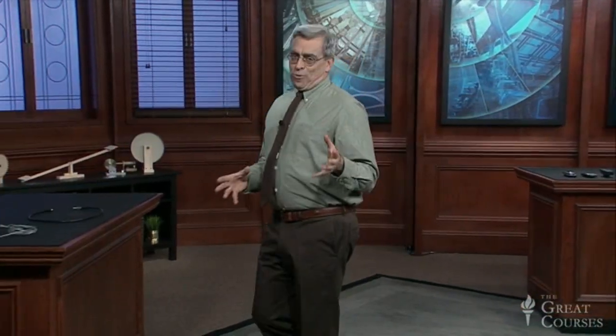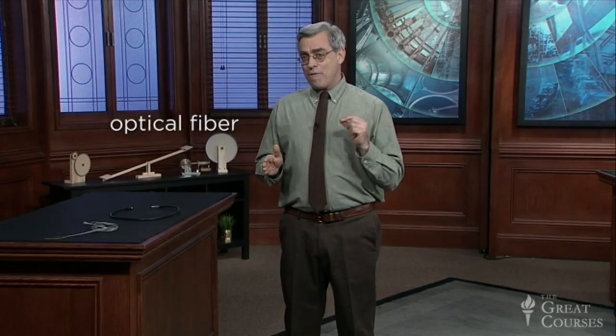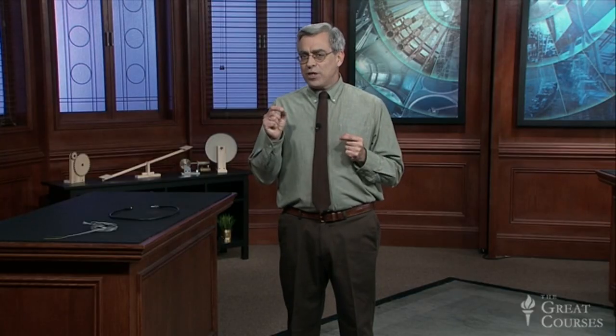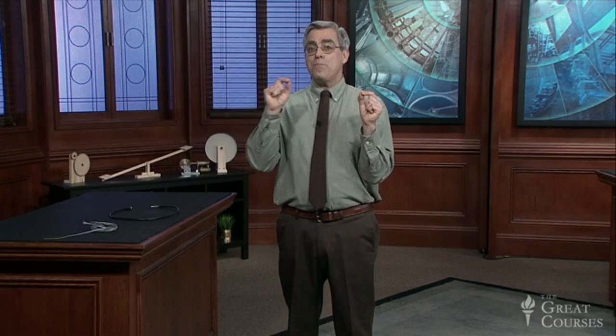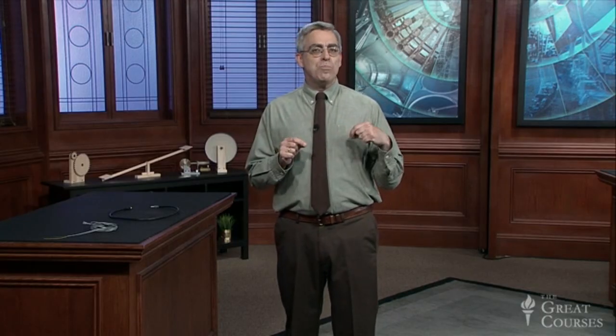But in the modern world of telecommunications, nothing is more remarkable than optical fiber. First deployed in 1979, fiber optic communication involves the transmission of a digitally encoded light beam through a tiny fiber of glass. The digital encoding is accomplished by a computer-controlled laser, which sends pulses of light through an optical fiber to represent ones and zeros.